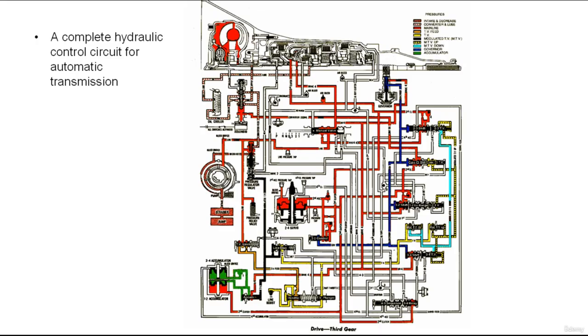And if we take a look at this figure here, it shows the complete hydraulic system as used in a 4-speed automatic transmission. Note the extra shift valves. The various hydraulic system circuits must be compact, and every possible means is used to avoid external tubes or other awkward fluid transfer arrangements. Many of the shafts and other units are drilled to carry fluid. So this schematic shows the transmission operation with the engine running and the transmission in park.